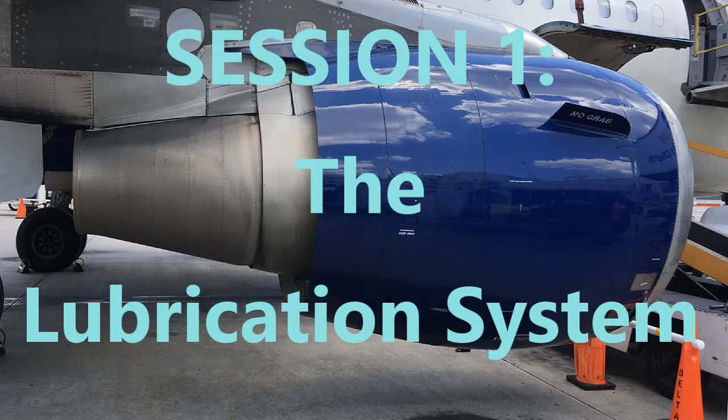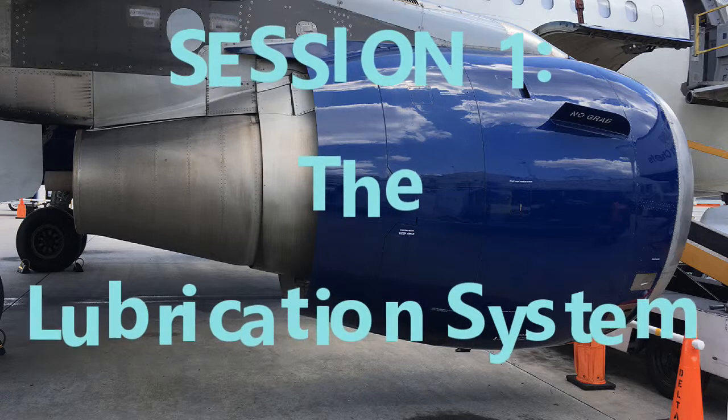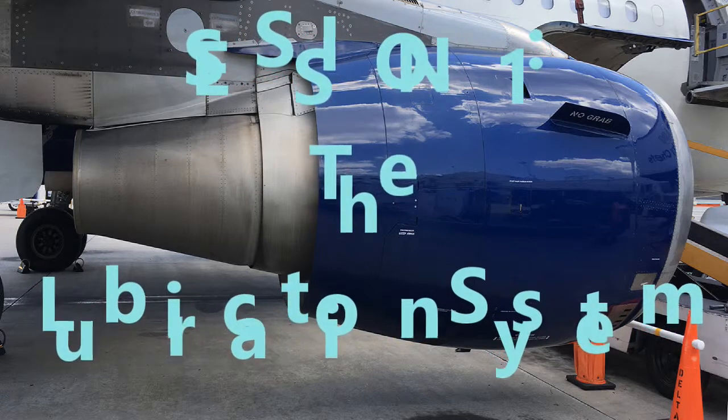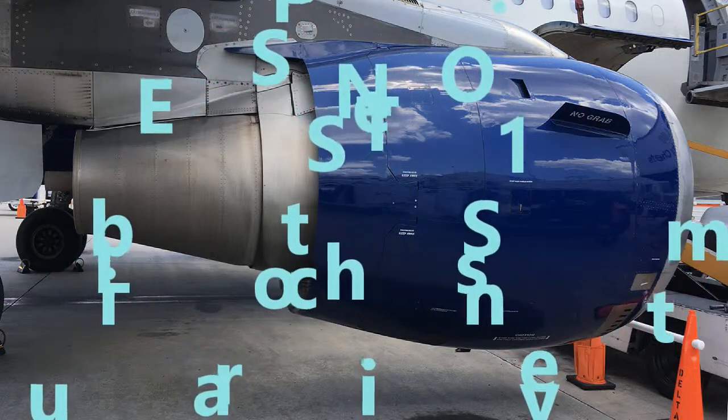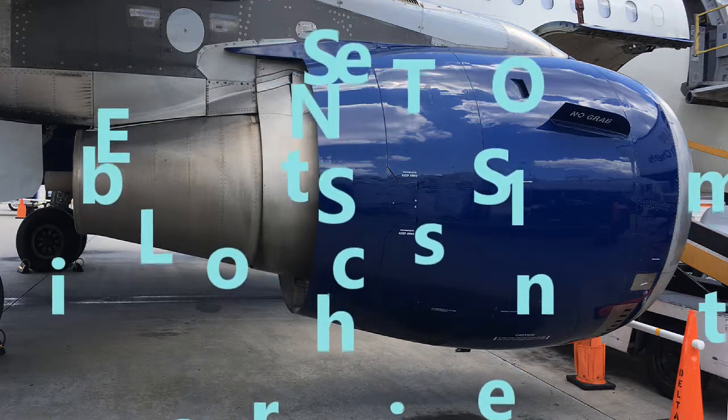And with the lubrication system, what do we need to lubricate? Okay, what's our objective? We have oil in the oil tank that's going to lubrication units, kind of like the middleman, saying, okay, I've got filters, but I also need a way to distribute that oil to what? Okay, what's our end result? Our end result is getting that oil, or the lubrication, to the components. In particular, we're talking about the engine bearings, the gearboxes. But not only is it for lubrication, we're also needing to cool some components, and that's another function of the lubrication.